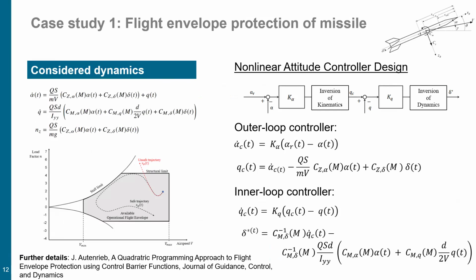So this is a very simple missile dynamic system. We have the nonlinear dynamics, and what we're trying to achieve is that the system will stay in a certain flight envelope, right? You have stall constraints, you have load constraints, and you need to make sure that the system stays safe. However, it's a missile, right? You have some sort of PNG law that is trying to intercept another missile. And for this PNG law, you have no guarantees that the loads that are commanded, or the NZ commands that are commanded, are staying within a certain range, right?